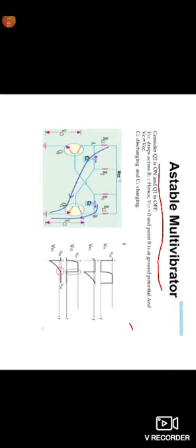So VC1 is equal to VCC, and the capacitor will charge up to VCC. Then it discharges through the base of transistor Q2, and C2 is also discharging towards point B to the ground. This is astable multivibrator case 2.